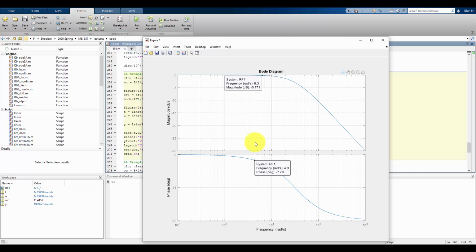So we want to be careful in our selection of the cutoff frequency and be cognizant of the Bode diagram, that signal at frequencies we think we want to keep are going to be far enough below the cutoff frequency that we're not introducing too much lag or reducing their magnitude too much. But on the other hand, we want the cutoff frequency to be low enough that we are going to be tamping down and really making a very small magnitude on the frequencies that we want to get rid of.